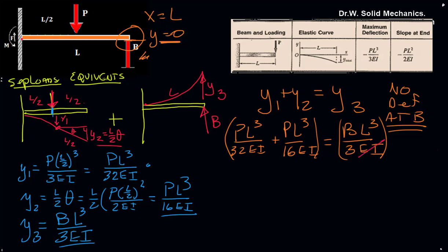We can multiply through by EI, and notice that these drop out. So the solution is independent of EI. This solution will be valid for any cross-section of material I and for any material that we picked. We could pick a very soft aluminum, or we could pick a fairly rigid hardened steel. We're still going to get the same answer.